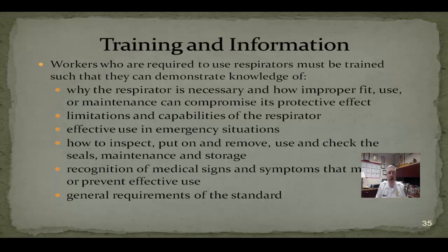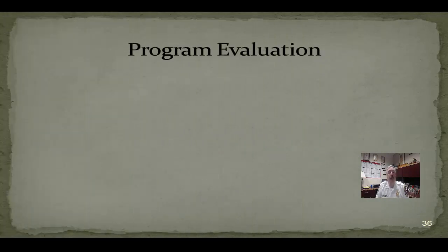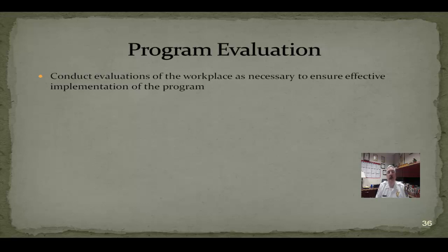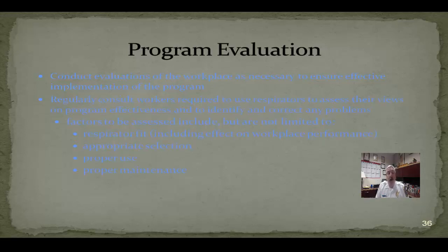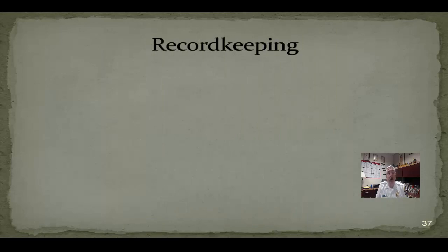Anytime that you're wearing a respirator, we've got to make sure that we're looking for signs and symptoms that may limit or prevent you from being able to effectively function in those areas. And then we've got to be looking at just overall general requirements of the workload. We've got to constantly be conducting evaluations of the workplace and making sure that the respirator that we walked into still provides us with the right protection that we're going to need for the environments that we're working in. We're going to be constantly looking to our folks. Supervisors should be making sure that we've still got a good fit, we've got the right respirator selection, that we're properly using them, and that we properly maintain the respirators that we have. We're going to keep records.